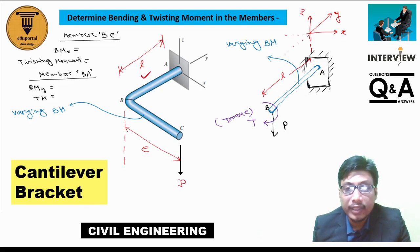One of the most important topics from where they frequently ask questions is the cantilever bracket. So suppose you are given a cantilever bracket like this, ABC, as you can see in the figure, with load P acting at the point C, and you need to determine the bending moment and twisting moment for the members. So how to do it?